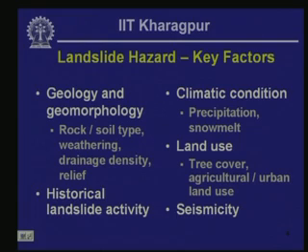drainage density that is crisscrossing across the area we are considering in our landslide hazard assessment, and relief, that means how steep is the countryside where we are trying to assess the landslide hazard. Second point that is of importance is historical landslide activity. So, areas where you have got frequent occurrence of landslide in recorded history, that area is likely to continue as area prone to landslide hazard.